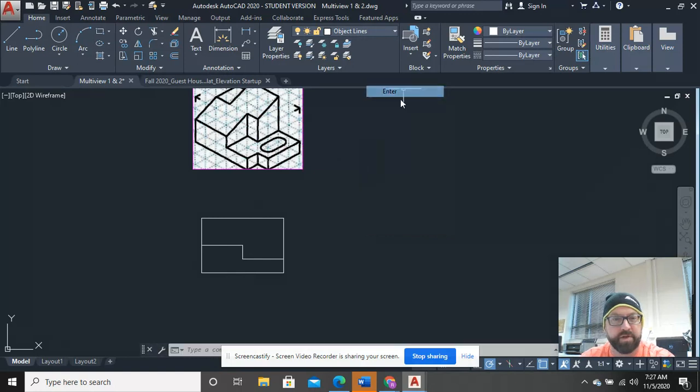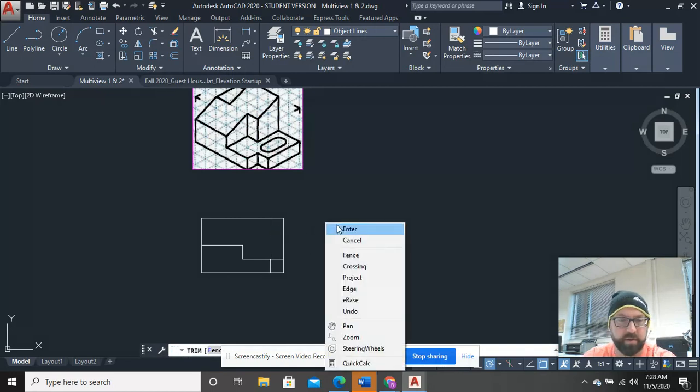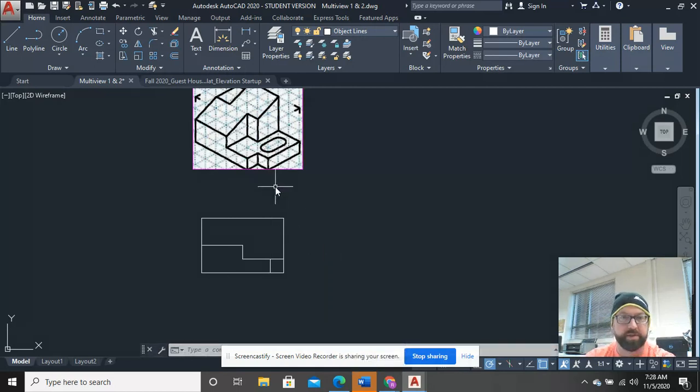And so far, you should see the exact same thing on this first face, with the exception of the fact that we have this one notch. It's so hard to do this because I'm like recording backwards, but this one notch, which is over 1. Okay, so easiest way to do that is just go offset 1 and bring that over, and that shows us the edge right here where that notch is taken out.